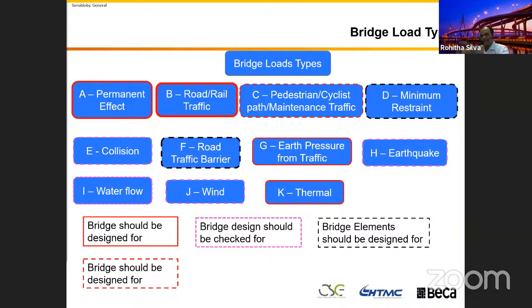So another thing you will learn: why did I put this slide in here? Why did I separate it into this one? You will see when you're going to do bridge modeling. I will give you a classic example. When you are building a bridge model, we put our piles and everything from the ground, because if you just ignore a couple of meters from the ground, below that, the lateral stiffness of the ground will provide significant lateral support to our piles and the behavior of the bridge. We can utilize that.